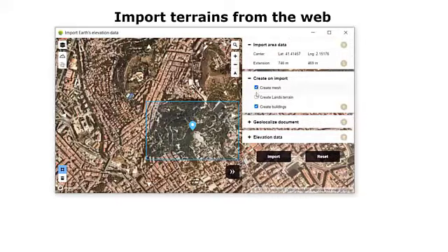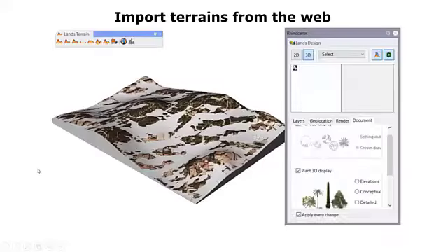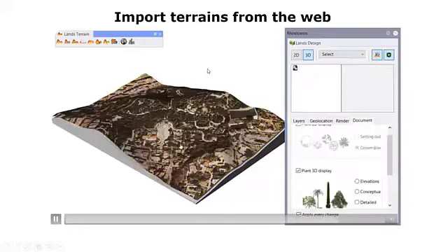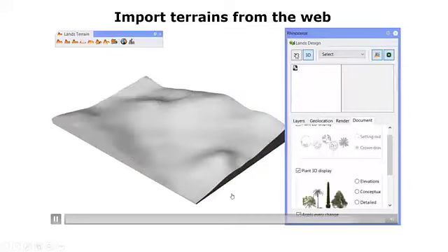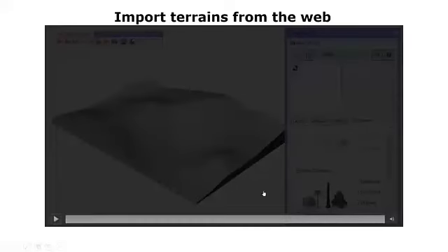The precision in this way is 1 sample each 30 meters, so it's useful for medium to large scale projects. In addition, you can insert the 3D mesh of the selected area, including the satellite image. You can convert the imported terrain, see that in 2D, and see all topographic contours that contain that selected area.